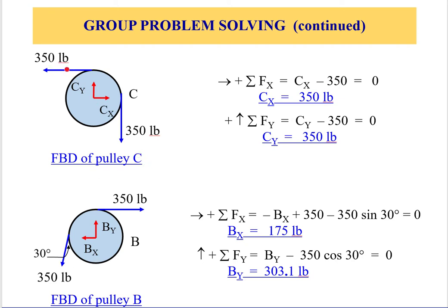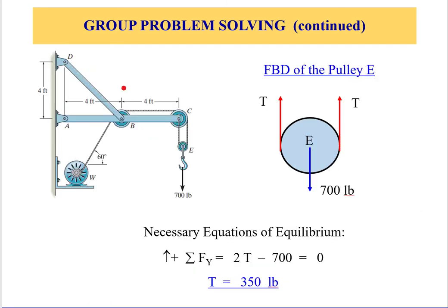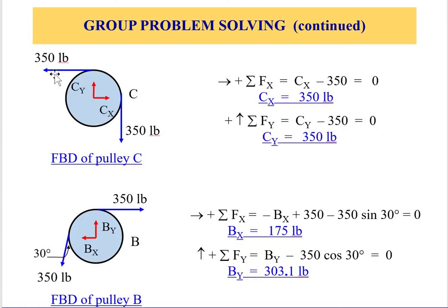The way we determine that direction, imagine you create a cut. If you're wondering how that is happening, you just create a hypothetical cut here, and the hypothetical cut will cut all the forces on that pulley. Do not mistake that beam here. This doesn't belong to the pulley, it's in fact attached to the frame, so that's not included. So we have only a force here and a force here, which you see labeled over here.